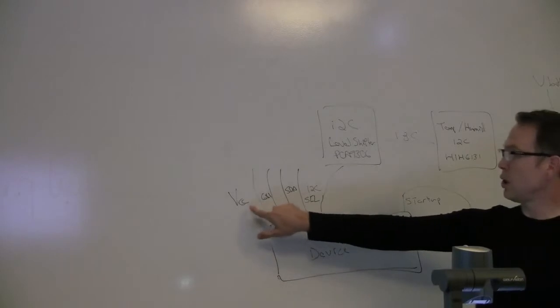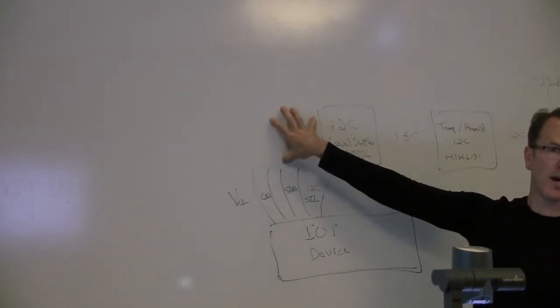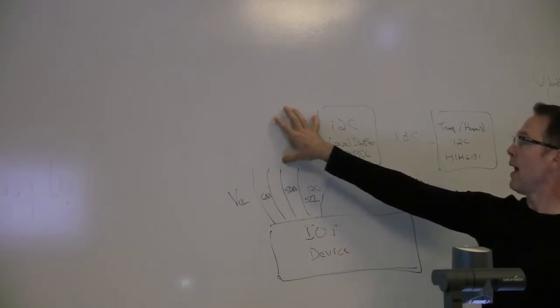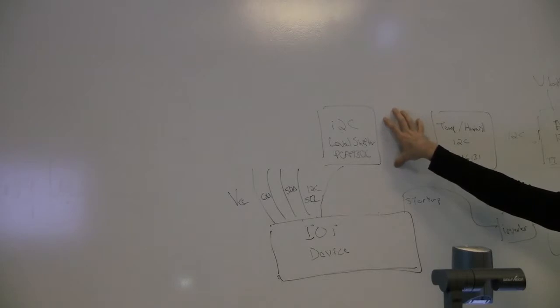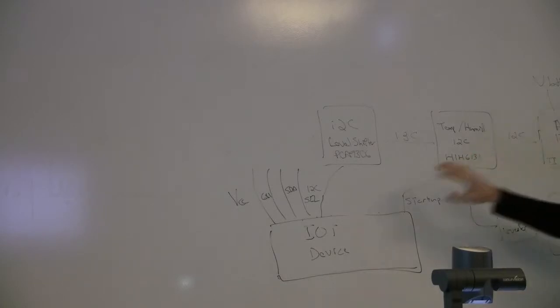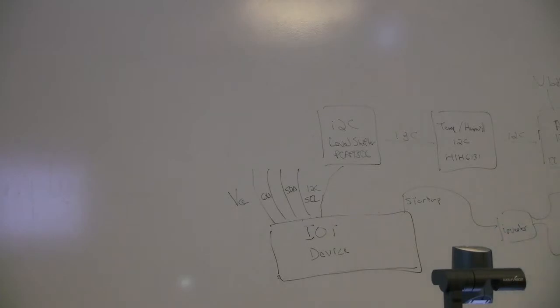What this thing does is it uses that voltage to establish this side, using the pull-up resistors on SDA and SCL, and then the board voltage is connected on this side. So whatever those two are, it just works out the difference. It doesn't matter; they could be the same, they could be different. So all the ones out here have to be the same, and the ones on this side have to be the same. Right, and then this thing will level shift between the two, and it's a cheap part and easy to put in.